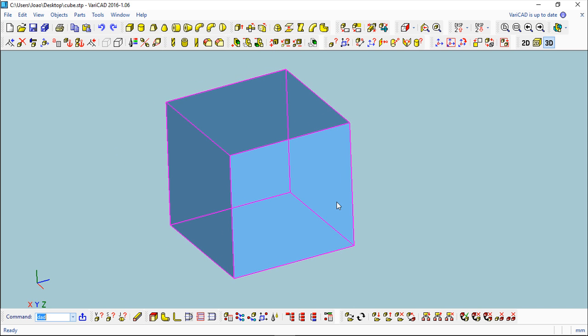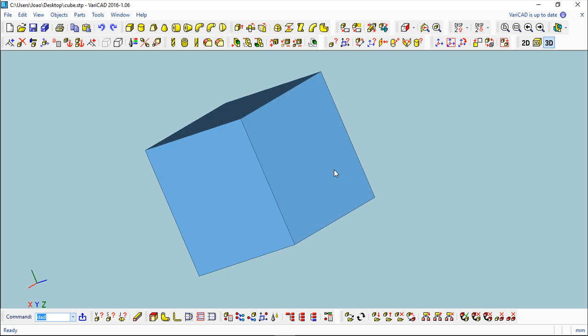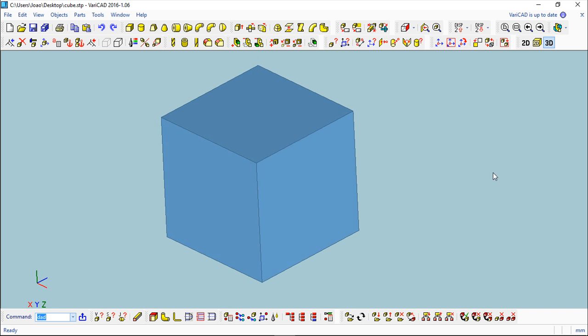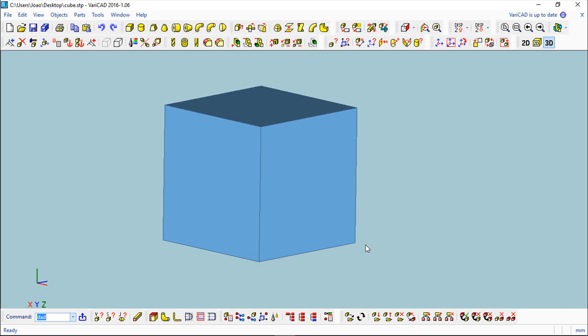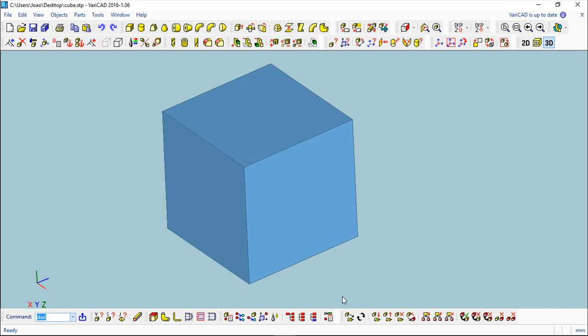This closed surface means that these objects are solids, perfectly closed and surrounded by patches, so you don't see the inside of this object. And each patch, each surface, you have 6 surfaces, has an outline created by a 3D curve, and each of those curves is connected to 2 adjacent patches. So one patch has a curve, mathematically speaking, and it has patches that connect to this curve.